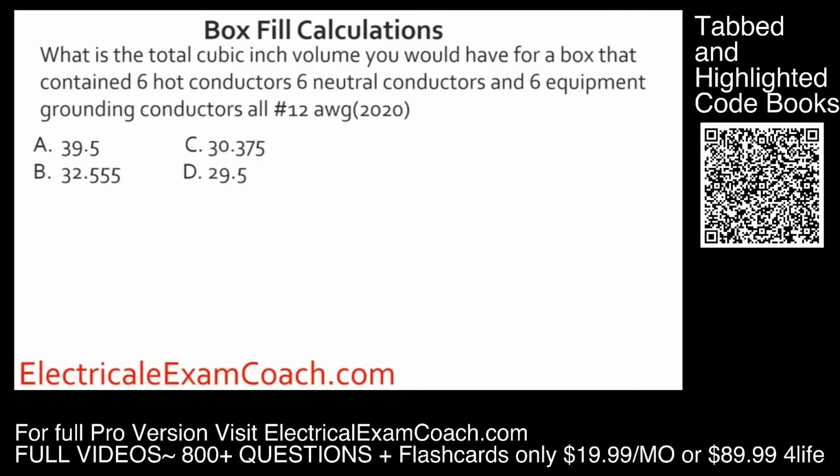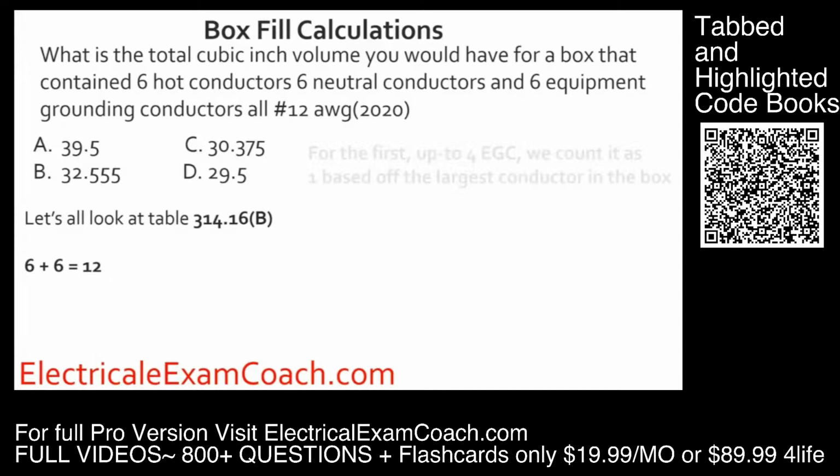What is the total cubic inch volume you would have for a box that contained 6 hot conductors, 6 neutral conductors, and 6 equipment grounded conductors, all of the 12-gauge persuasion in the 2020 and the 2023? First thing we're going to do, we know we take the 6 hots and the 6 neutrals, and we're going to set that to the side. Now we got to deal with the equipment grounding conductors.